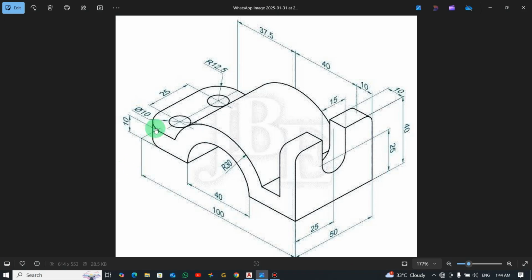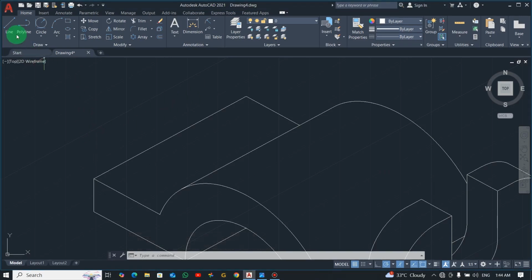So the same procedure, also 12.5. Pick the line command from this end point, just drag 12.5, enter, come inside 12.5. Good. So this is the center of your circle. So ellipse, EL, I for iso circle. Now click here.